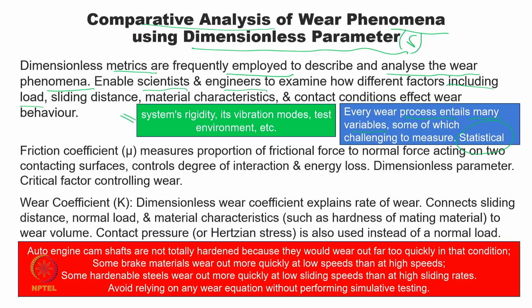So, why not account for the wear coefficient? If we are getting repeatable results, we rely on that. And again, we say that it is not an absolute value, it is just for comparison purposes. So, it gives a qualitative comparison among some materials or some lubricants. That is why we are using this kind of non-dimensional number.